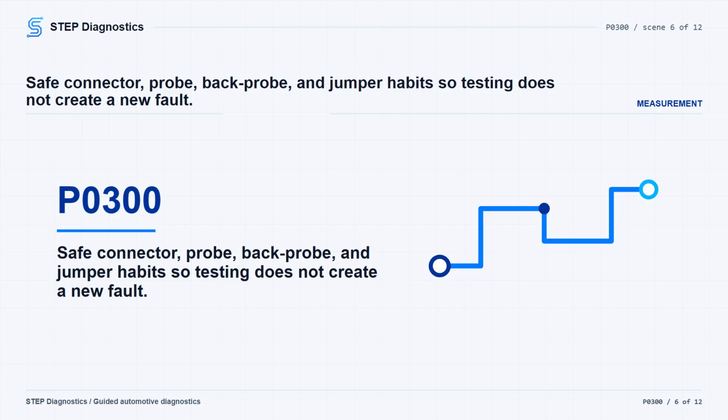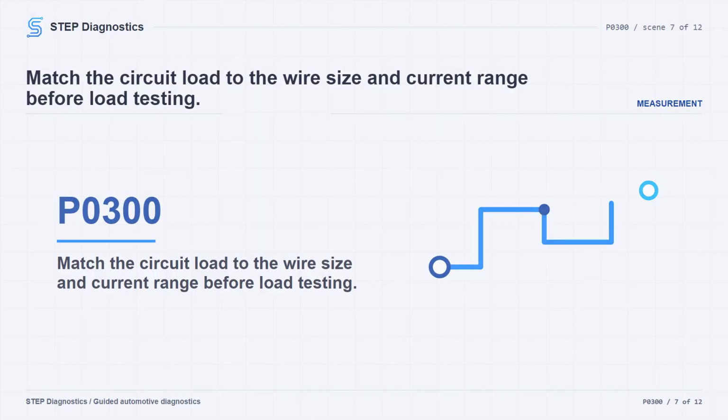The recommended universal testing jumper wire fuse is 5 amperes or less, and flex probes are not intended to carry high current greater than 5 amperes. Do not apply power or ground directly to module-switched components unless the diagnostic path specifically calls for it. When the electrical path calls for circuit loading, match the load to the circuit.